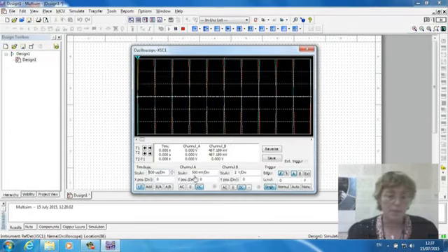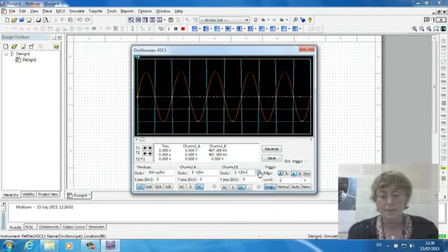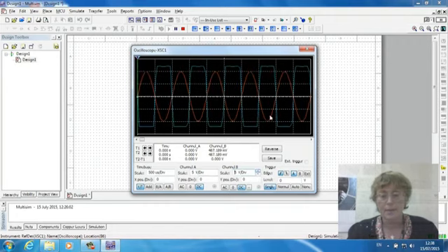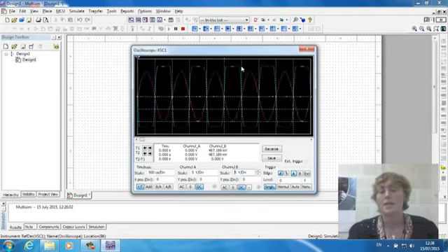So all our signals are much bigger. We're going to have to change our volts per division to be able to see them, to make that a bigger number. 5 volts per division, yeah, 5, 10, that seems fair enough. And let's change that as well. So we're on 5 volts per division on both, and you can quite clearly see that the blue trace has a flat area at the top and bottom where the amplifier is saturating. It's unable to give us any more voltage.